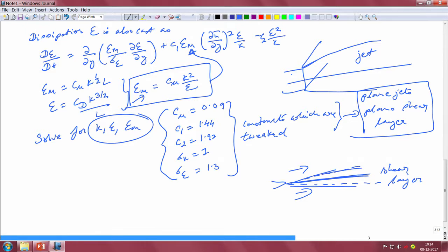But again remember that when you did an average of the Navier-Stokes equation, and when you modeled these terms using K epsilon and things like that, or Prandtl mixing length model, you are basically not resolving any of the Eddy scales at all. So, when we started with turbulence, let me show you this particular plane jet. So, you have got lots of these eddies of different sizes.